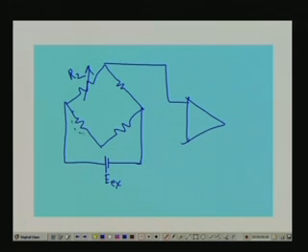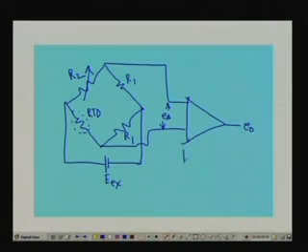This is our RTD, this is R2 and this is R1, this is also R1, this is our RTD sensor, right. Now, an instrumentation amplifier is necessary because the output voltage is very small. This is our Ea, this is our output, and this is the instrumentation amplifier, right. A variable resistance R2 is necessary so that the bridge remains balanced at 75 degree centigrade.